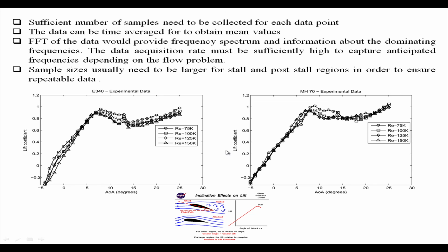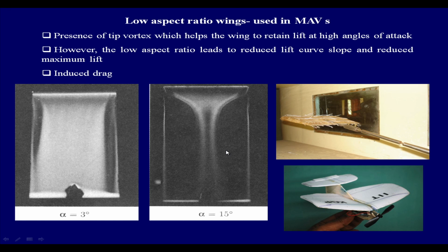So, these are obvious things though. Now, if you look into the finite wings, that means you use the same cross section, but make the wings finite. So, you allow the tip roll up, as we say. When you put the model into the test section, the flow can roll up from the end here and there, and then the aerodynamics changes very drastically.